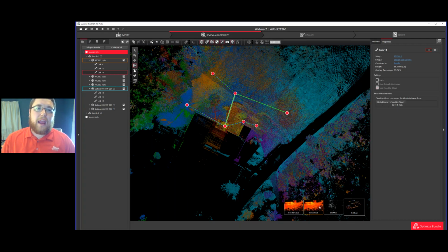But in those cases, I usually would still fall back on making sure I have 3 control points between my scans, so I can link my scans together that way. It's just a safety net fallback if I know cloud to cloud is going to struggle. Or I just make sure my scans are a little closer together so I have a better overlap.